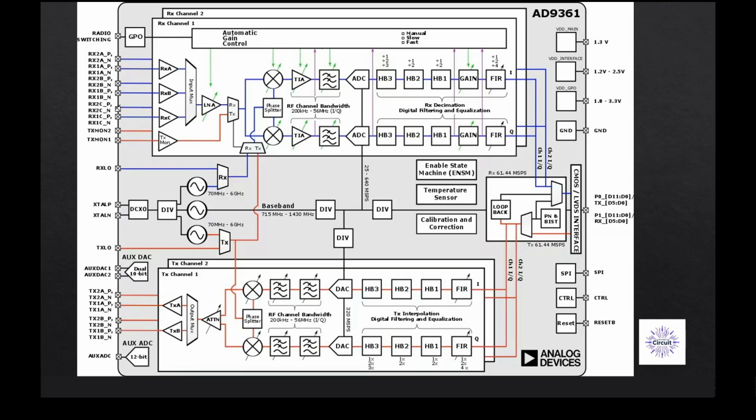Either we can create that phase mismatch at a high frequency, after our mixer where the signal is at high frequencies, or we can create that delay or time mismatch at baseband before it's up converted to higher frequencies. This is definitely a design choice. Each one has its advantages and disadvantages. We'll make sure to go over that and also see how the integrated circuits for those are made.